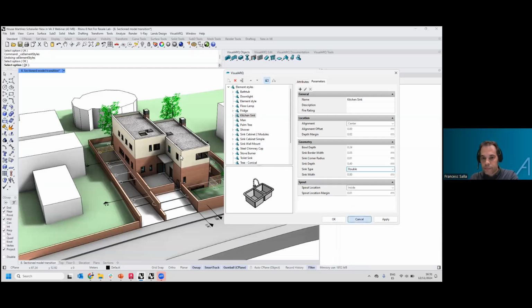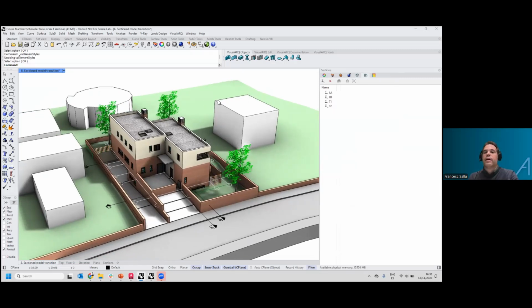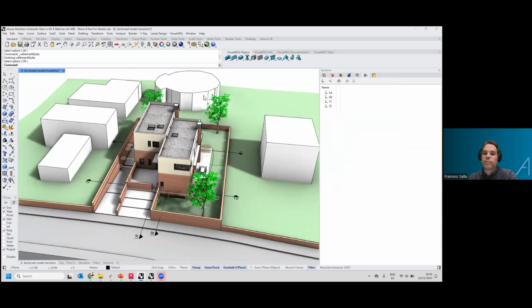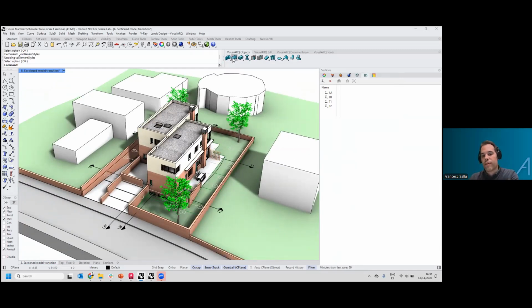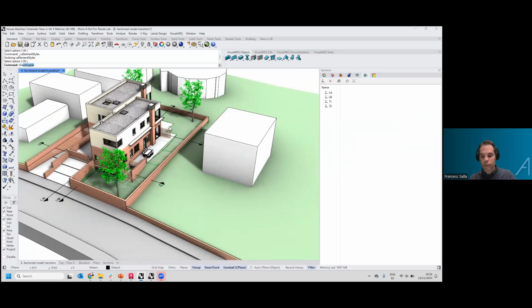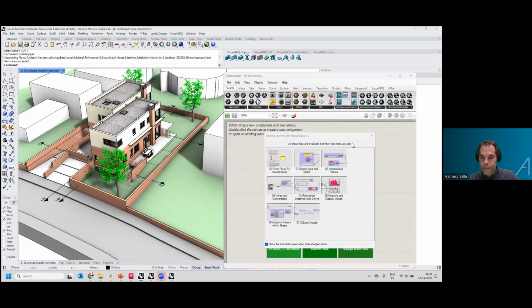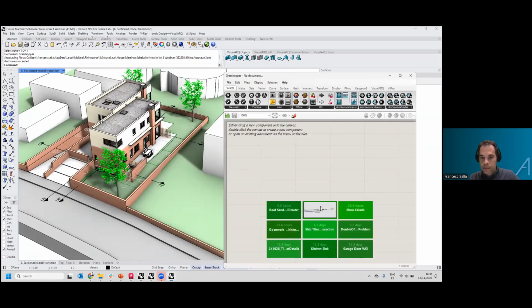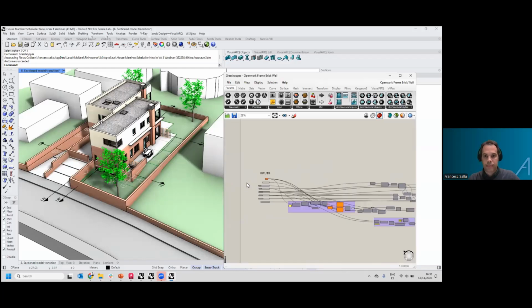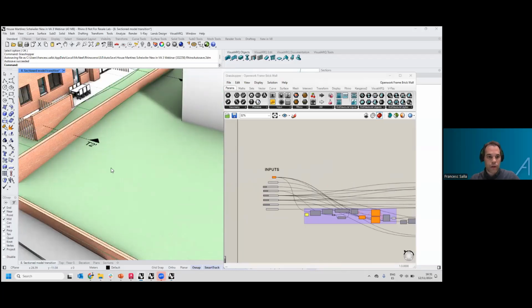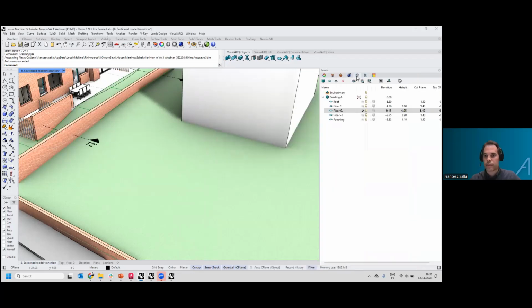All right. I'm going to cancel this. But again, all these objects that I have shown are driven by Grasshopper definitions. But now it is possible also to create walls and curtain walls from Grasshopper styles. And I'm going to show you an example of that for a wall. So I'm going to open Grasshopper. I'm going to open a definition that generates an open work frame brick wall. So I'm going to draw here a rectangle, just a curve to give that wall preview.